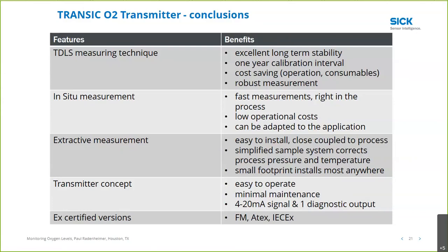I have a further comment. This is Matt Diggs. Yeah, that would not be an ideal location if it was at the exhaust, like where your CEMS measurements would be. You really want to be closer to the firebox for speed of response for combustion efficiency, combustion control. The key word there is, and the question was, in the boiler exhaust. I think you really want to be closer to the firebox.